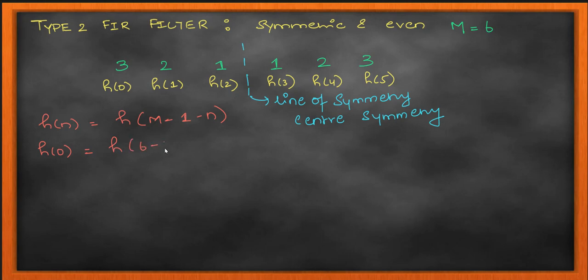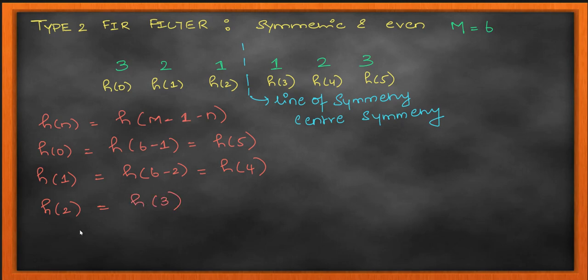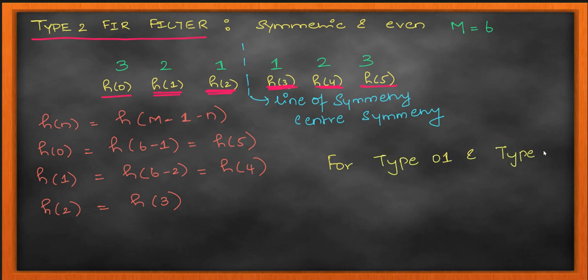That is also the most commonly used filter, or at least in my experience I have used the type 1 filter most in designing some noise filters for audio. I go with type 1, symmetry and n equal to odd. And like I said, for even, the only problem is the line of symmetry goes through somewhat of the middle. It doesn't go through a sample point, and that middle point is mostly at index 0.5, right? So you are looking at a fractional index, and then solving it or coding it becomes a little more difficult. So I prefer symmetry and odd.